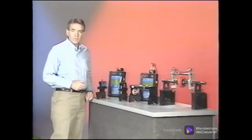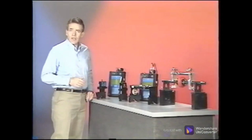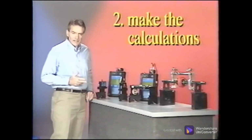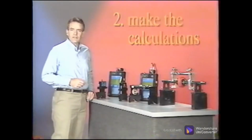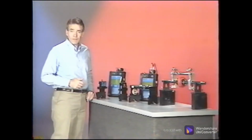Earlier, we reviewed the alignment methods and noted the differences among the methods. Although they seemed very different, they all have the same 3 steps. First, measure the misalignment, and next, make calculations, and then adjust the machine. Even Bo and Boo performed the same steps.